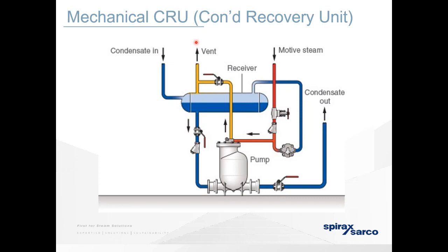Yeah, so you can use your flow meter. Again, like I said at the beginning, you're going to have almost 100% return because it's all cold. But it will depend on your process, so you will see losses. The reason I'm struggling with the question is, as a rough rule, we would use 25% losses. But there are other processes that will lose more, and others that will return more. So I'm trying to think of the best way to calculate it.